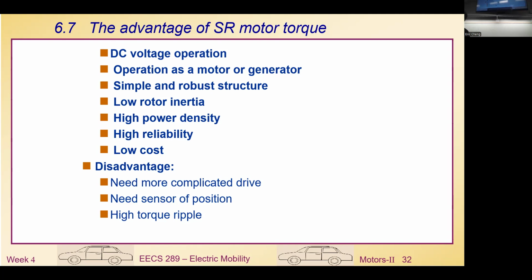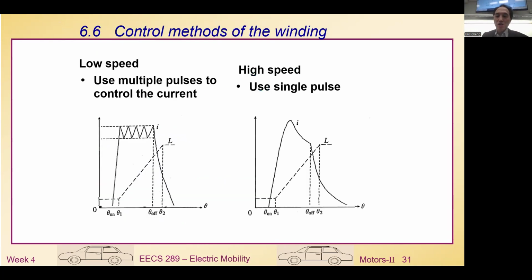Because of this, the torque ripple may be higher. Yes, this motor is famous for high torque ripple. You can see that this current relates to the torque, and this is constant torque. When the current is decreased here, this is also related to the torque. So we get very nice torque here. But from phase to phase, we pass through this region, where the torque is not linear. That's why we get good torque, but suddenly we get lousy torque here.